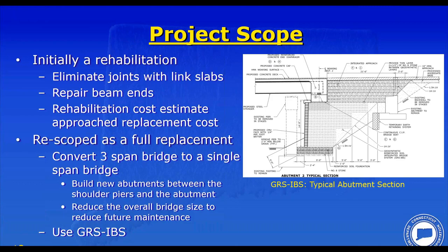Okay, and then normally in a mechanically stabilized wall, your reinforced fill is like a block. It's rectangular as far back as it goes, and this is stepped. Is that correct? Yes, that's correct. That's another aspect of GRS IBS where you can design it with these steps where you don't have to have the full rectangular reinforced zone, although some people do it that way. Federal Highway had recommended that the step procedure could be used, and we went with that. It sort of follows a failure surface. It does make construction easier if you do that.